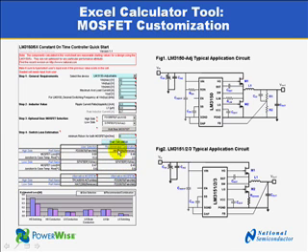And then you can decide whether you want to go with that part proposed by the system or your own part. And it will give you a chart that shows you high side switching, high side conduction losses, low side conduction losses, low side diode conduction, and so forth. So it lets you see how good is your own selection compared to the recommended selection.